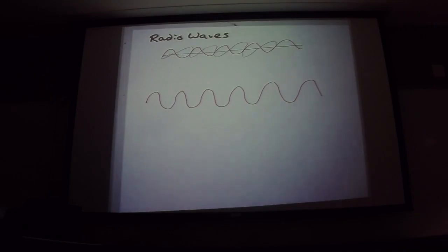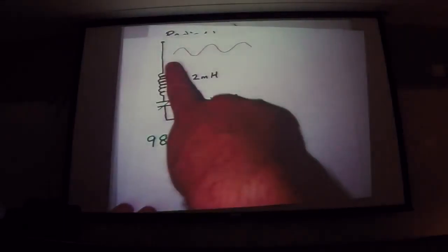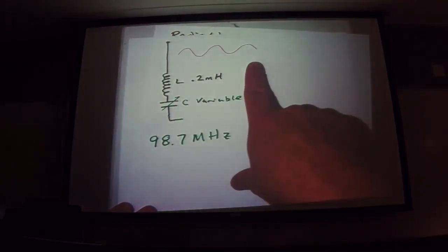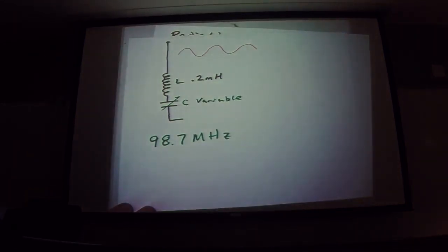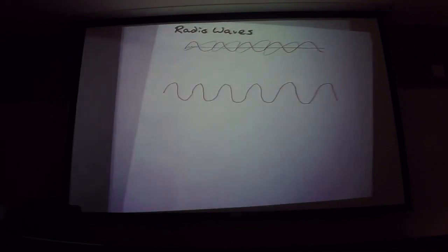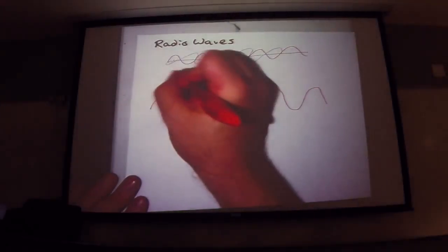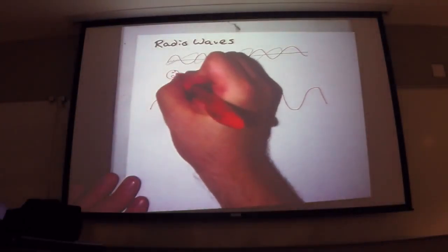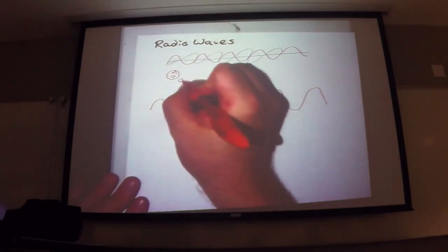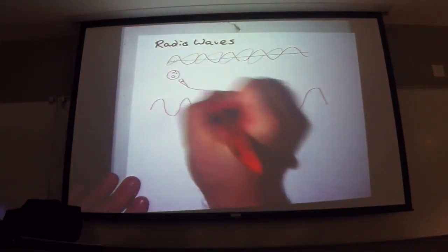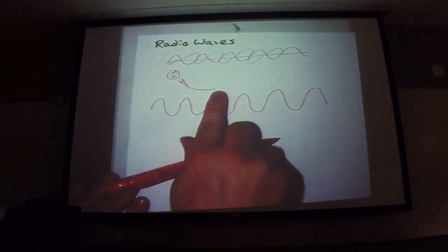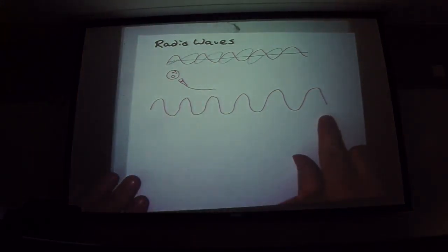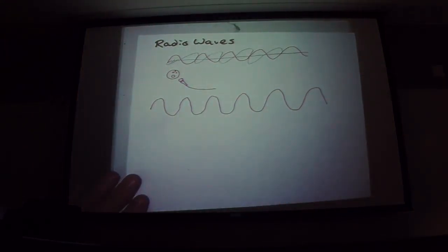Then what happens is your tuning circuit resonates with what we call the carrier wave. The carrier wave is what you tune to. The electrical pulse is then what you end up hearing. So here you are at the radio station. Microphone turns this into electrical pulse, which is then added on to the carrier wave. And there's two different ways to add it.